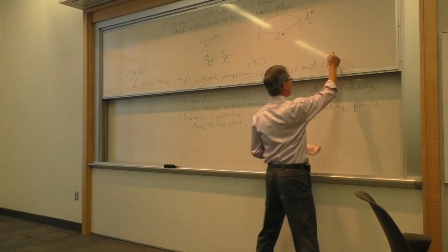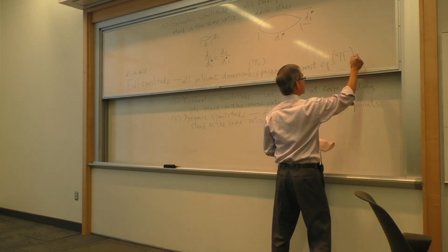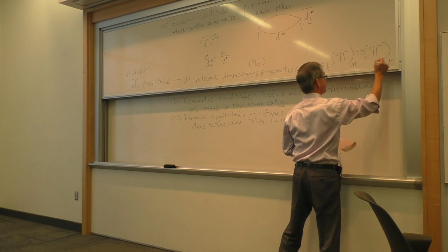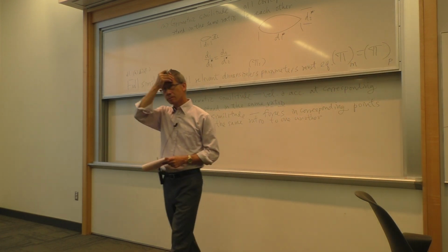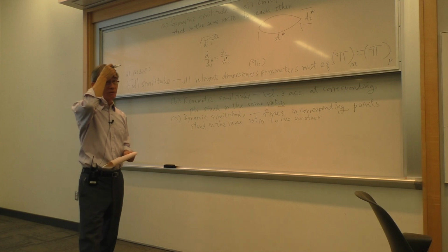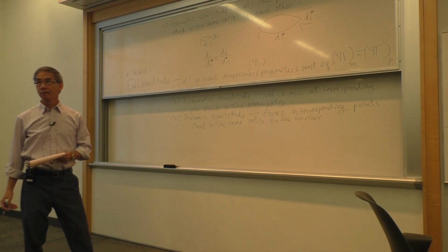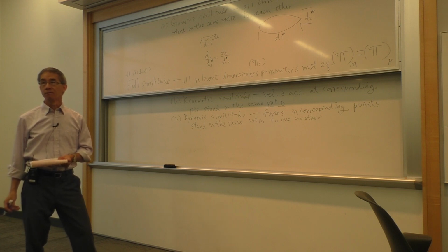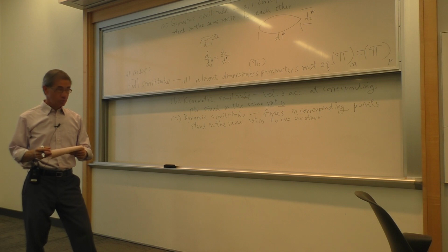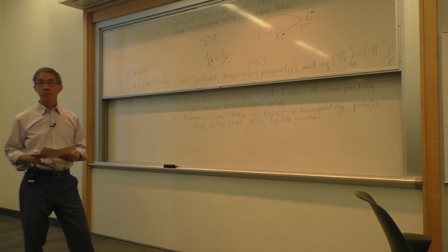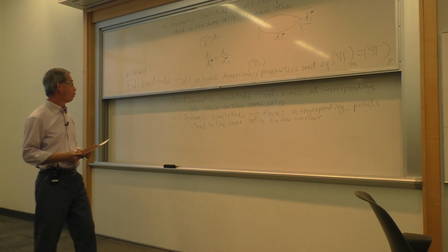In other words, the pi terms, choose one: Reynolds number, drag coefficient, relative roughness. On the condition that A, B, and C are met, all those pi terms must equal each other. That's very powerful. And that's how we will use this to do model testing. Why is that?